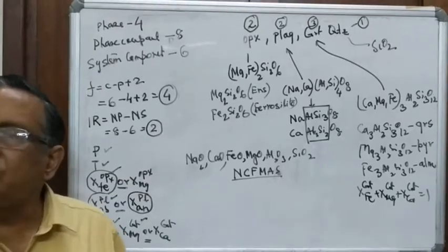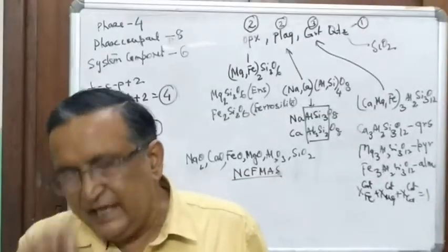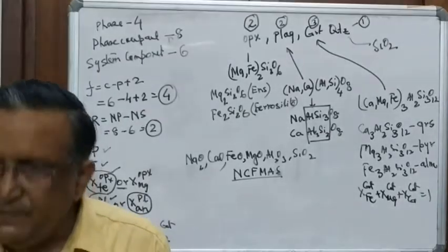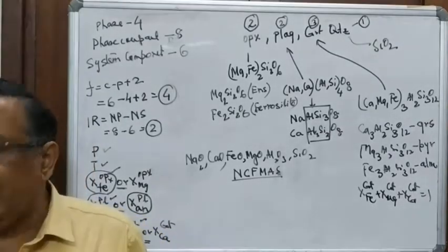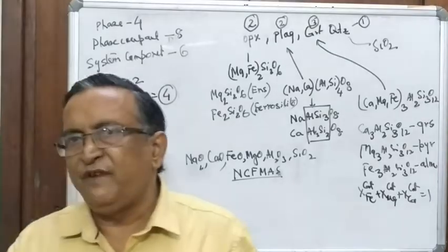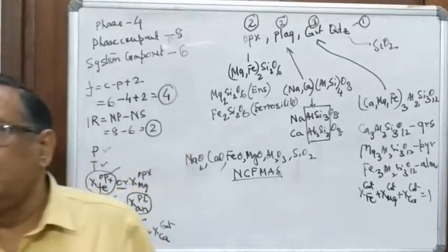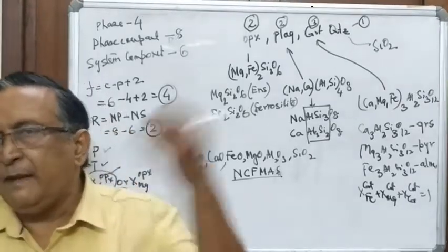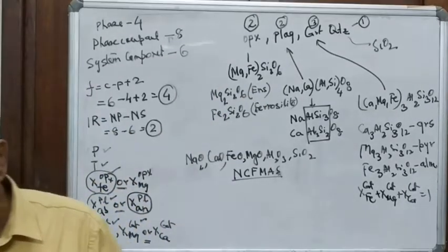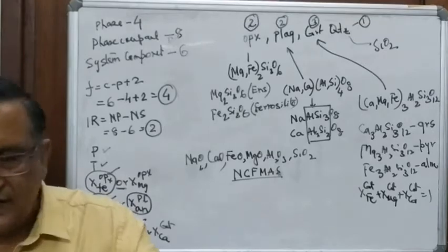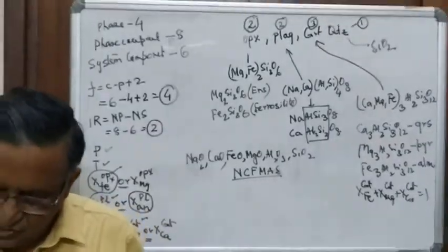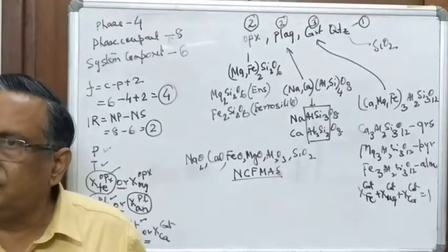The beam diameter is 1 micron, and the area of influence is roughly 2 to 3 microns. There's a huge electric current at around 20-25 kilovolts. It excites the surface and it emits X-rays. So you have X-rays for iron, magnesium, calcium, whatever elements are there, it throws out the X-rays.